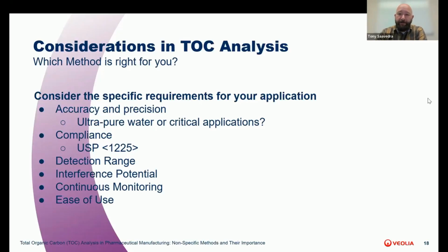We also need to talk about interferences. Membrane conductometric is least affected by these, followed by NDIR. But there are ways to deal with that, right? Direct conductometric is most susceptible to interferences, especially from non-ionic compounds.